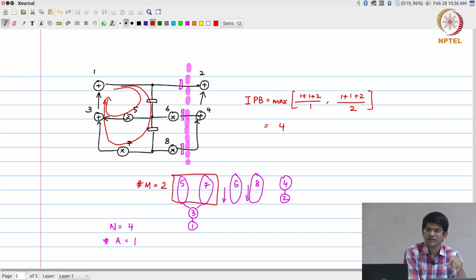In this case, that is not really what I am concerned about, because I know that my critical path can only come down to 4. So I do not really need to worry about balancing the different parts of the pipeline. Over here, my only goal in pipelining was to reduce critical path to 4 and break some dependencies so that some operations can be moved around.